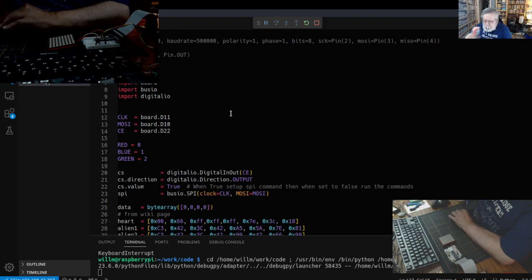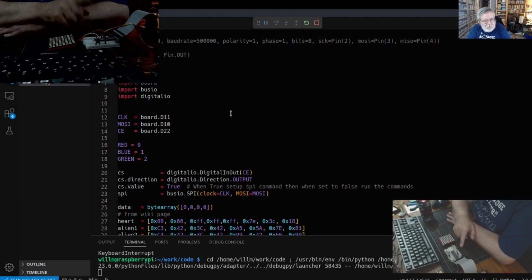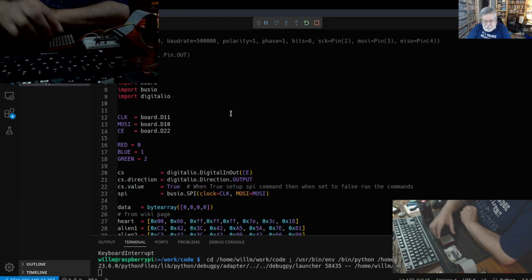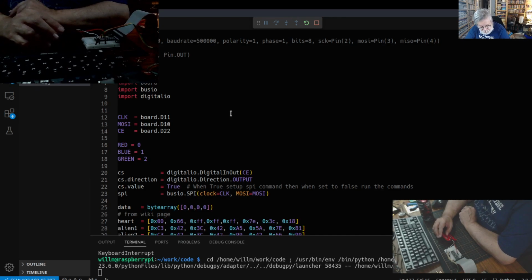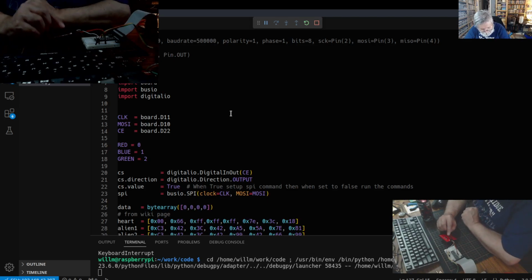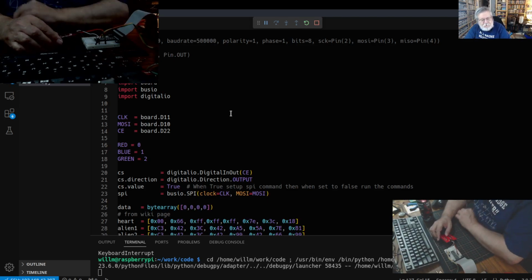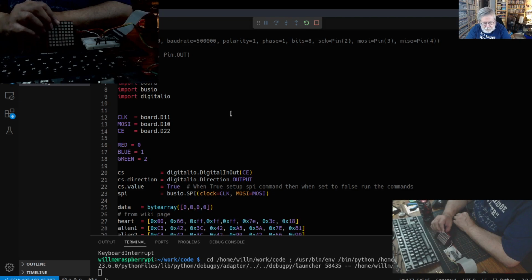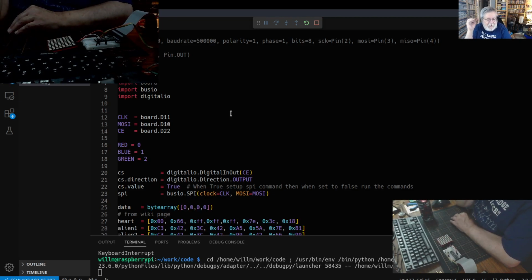So once I had everything set up and I was connected, I pulled out the code off the microcontroller and I adjusted it to run on the SPI of the Raspberry Pi. Because in this, this is interfaced via SPI. You have voltage, you have ground, but you have what's called clock, CE, and MOSI. Sometimes the CE will be called CS. But basically the clock, it times everything. The MOSI is